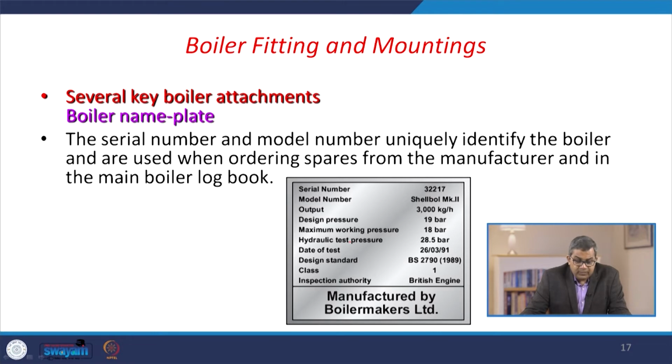One of the key items among the boiler fittings and mountings is the boiler nameplate. This is not only a nameplate, but it also provides valuable information: up to what pressure you can handle this boiler, who the manufacturer is, and who the certifying authority is. If you are moving that boiler from one country to another, then you need to take some additional certification under the targeted country's regulations, etc.